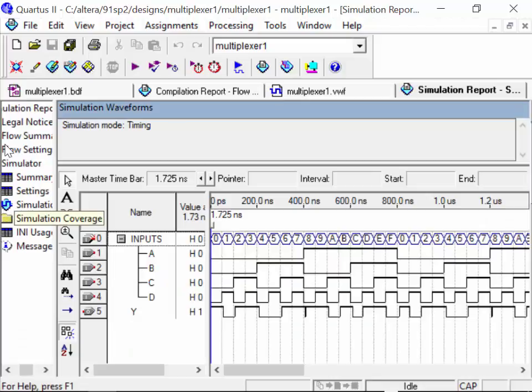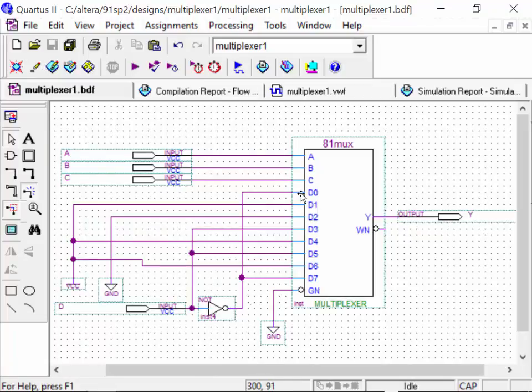All right, let's see if it's looking right now. So now we're at 1 0 1 1. Should be 3 zeros. All right, it looks like there's a problem here earlier than that. Let's go back and look at my circuit here. D0 should be connected to D naught. D1 should be connected to VCC. D2 should be connected to ground. D3 should be connected to D, but it's connected to D naught. See that?